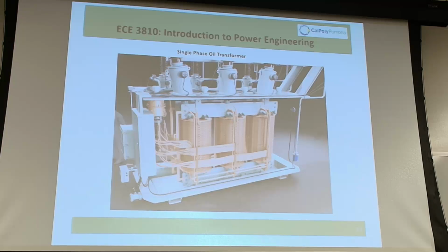So here you get the full voltage from this point to this point, but if you want to, you can actually increase it, right? You can have a plus 5%, minus 5%. What I mean by that is you can have this device tapping the winding on different spots, right?